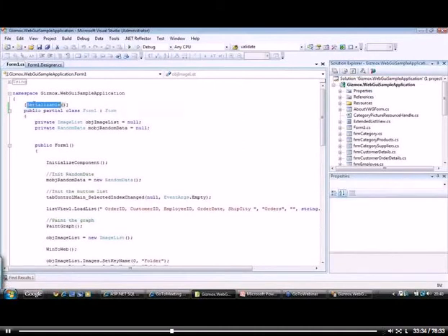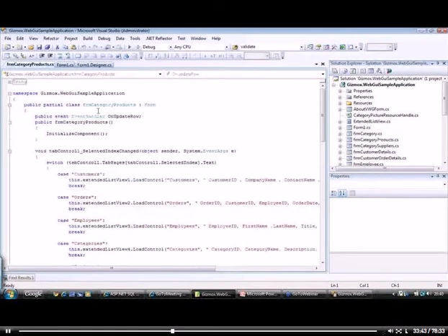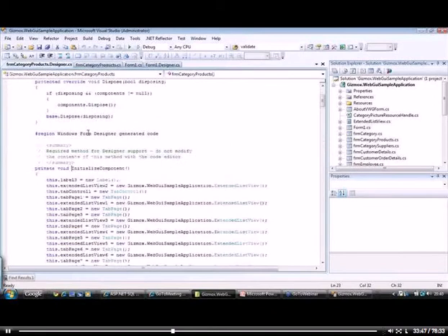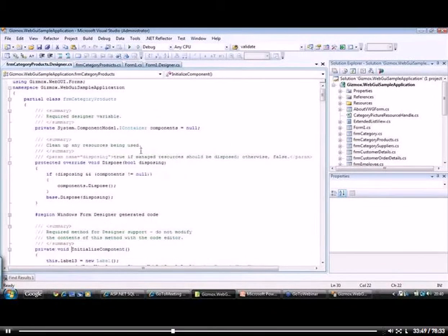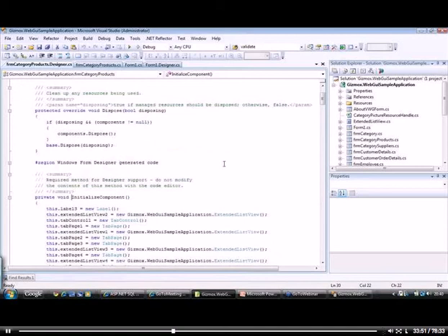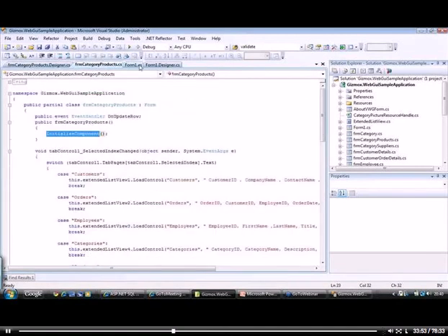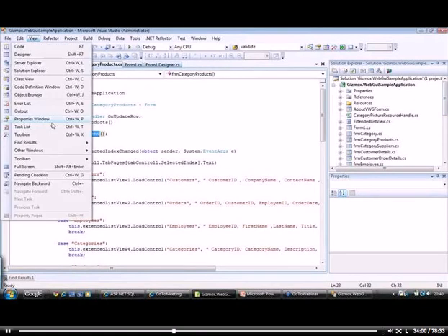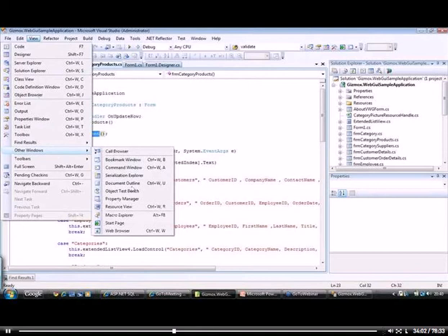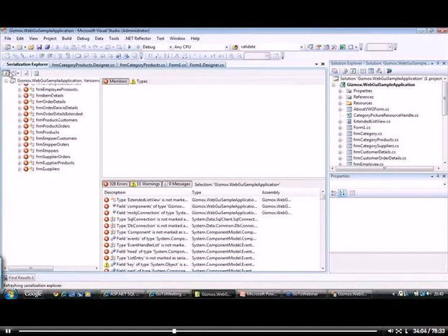So as you can see, I have this serializable attribute here, and I'll probably have it on any other form. So I have serializable on every form, and then what I need to do is to reopen the other windows, reopen the Serialization Explorer, and refresh.